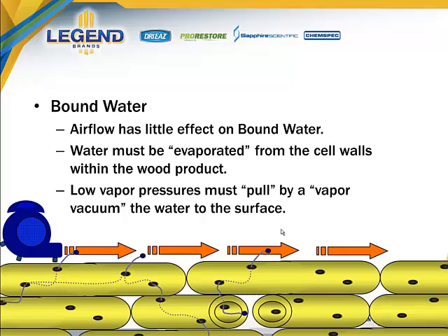Most studies and most peer-reviewed documents will show a reduction of about 70% in airflow and still be able to maintain that balance from the free water drying phase versus the bound water drying phase. If you want to go out and do some research on the topic, very commonly in the building science community, the material science community, they're going to refer to the difference between these as what they call the constant drying rate versus the falling drying rate.